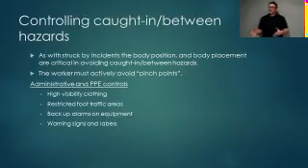There are barricades that can be set up around crane radiuses and excavator radiuses, but more than that, the worker, him or herself, needs to be aware of where they're placed in regards to equipment and pinch points. That's one of the things we try to teach our guys, being aware of where they're at.